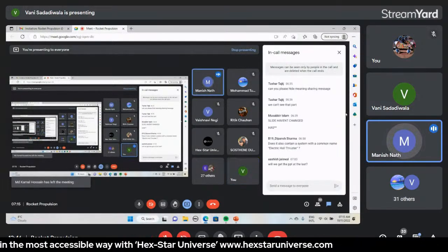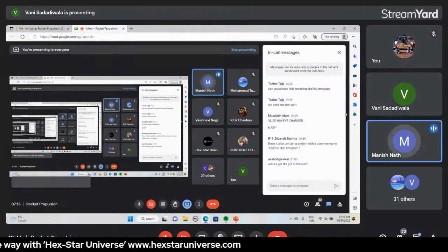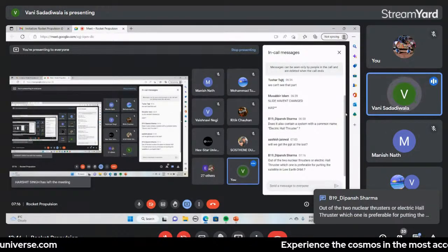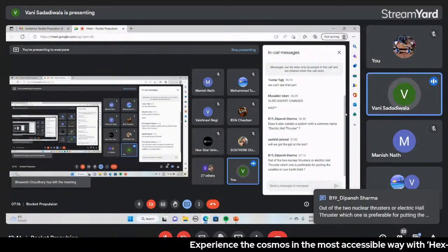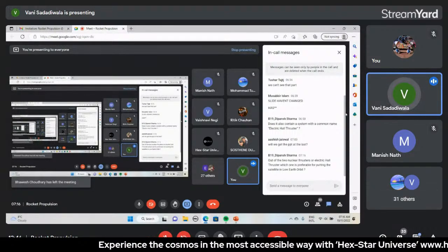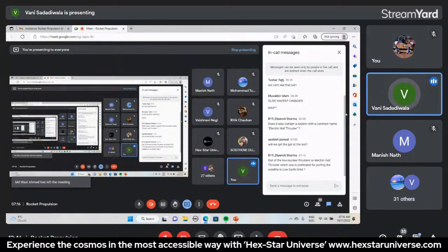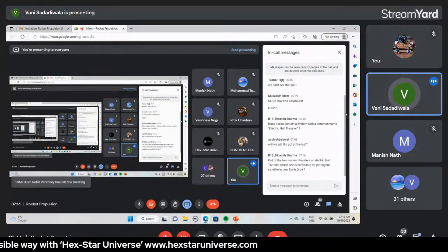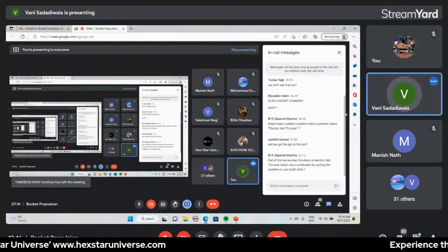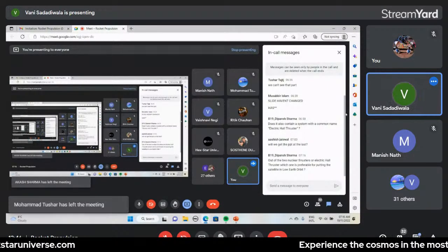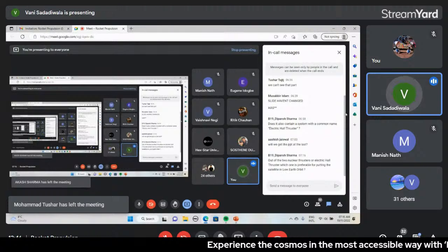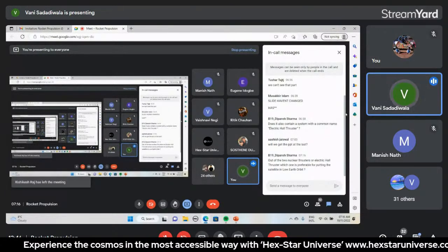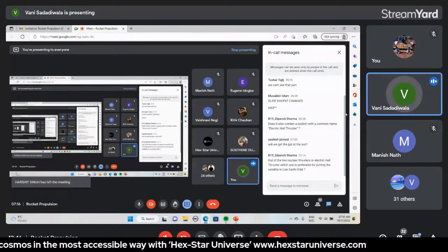Okay, we also have another question from her. What is the most effective nozzle configuration? Yes, so if I talk about the most effective, it is the bell type, because of the divergence angle and also of the suitability with the throat area and the divergence area at the nozzle. So there, as I mentioned, there are two sections, that is throat and the nozzle exit area, which basically deals with the divergence angle of varying type, that is from smaller to bigger type, and hence due to the advanced and easy manufacturing of bell nozzles, they are highly considered.